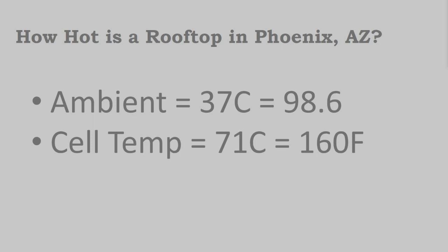And so it's very possible for wires on a solar array or on your rooftop to get to a temperature beyond 75C. So if they don't have that 90C rating, they could start burning up on the rooftop.